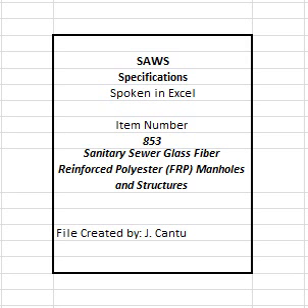853.3 Submittals. Contractor shall submit manufacturer's product data, instructions, recommendations, shop drawings, and certifications. All submittals shall be in accordance with engineer's requirements and shall be approved by the engineer prior to delivery. 1. Submit proposed methods, equipment, materials, and sequence of operations for sewer construction. 2. Plan operations so as to minimize disruption of utilities to occupied facilities or adjacent property. 3. Submit all test reports and pre- and post-sewer television inspection video. 4. Videos become property of SAWS.